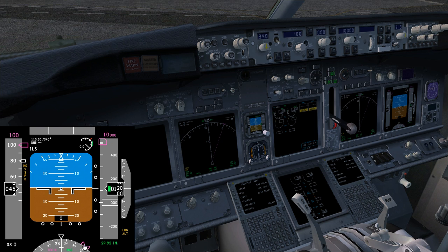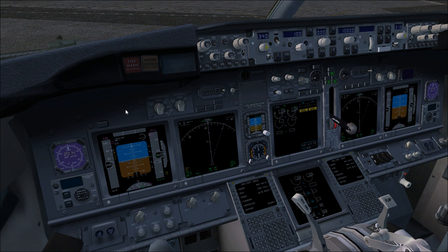Going down here, we have the heading scale. Here there is the heading scale. The same heading is actually set here in green. You can see MAG indication. Actually, this is the magnetic heading. In case you have the ability to switch to true north, and so true heading, in case you are flying near the North Pole or South Pole, Antarctic or Arctic. The last thing you can see here is actually the heading selection in magenta. We have a digital readout of the actual heading selection and a scale selected here and a selector. This completes our primary flight display indicators on the primary flight display.